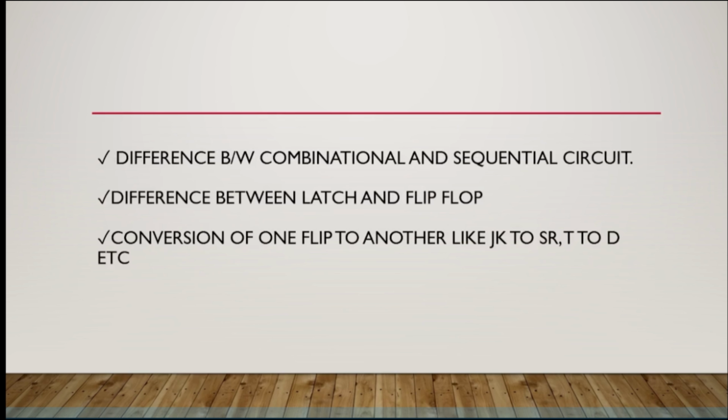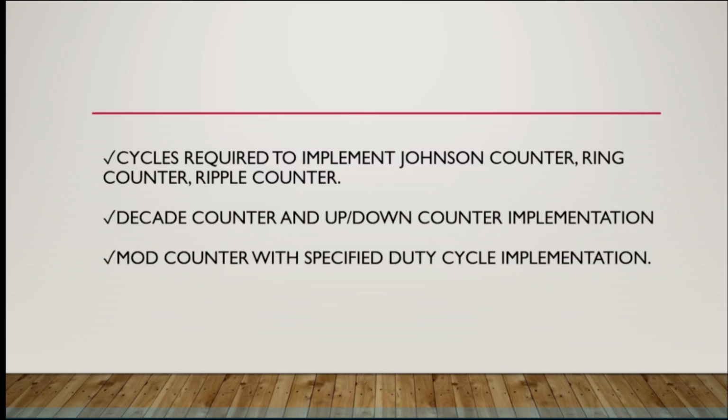And then after this you need to know about counters, like how to implement a counter. You have various kinds of counters like Johnson counter, ring counter, ripple counter, up down counter, right? You need to know how the implementation of all these counters happens, like a mod counter with a specific duty cycle implementation. So you need to know these various kinds of counters in digital electronics, right? These are very important concepts within digital electronics.